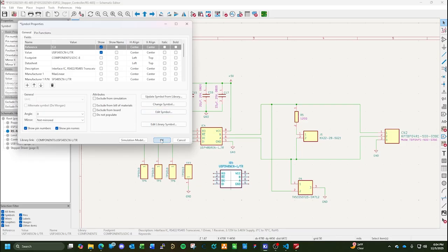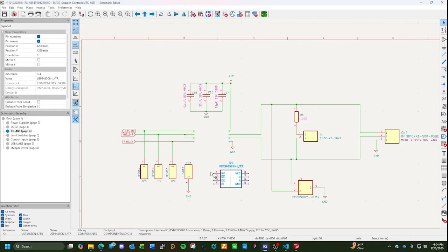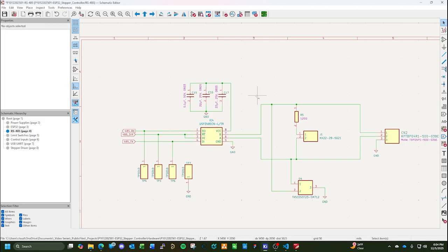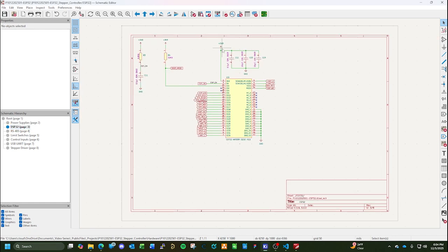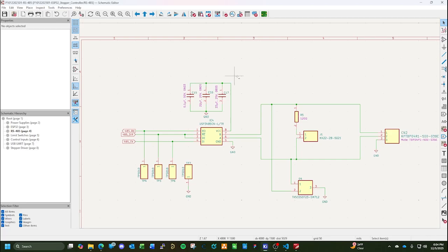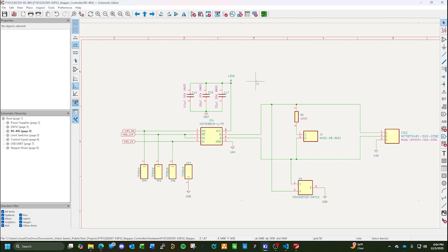It may complain about it, but it doesn't matter because what we're going to do is pop this guy out, put this guy right in his place, plumb it up, get rid of the 5-volt supply. So let's go over here and grab 3.3. Go back over to here. Bam. So now we have a 3.3 volt operating